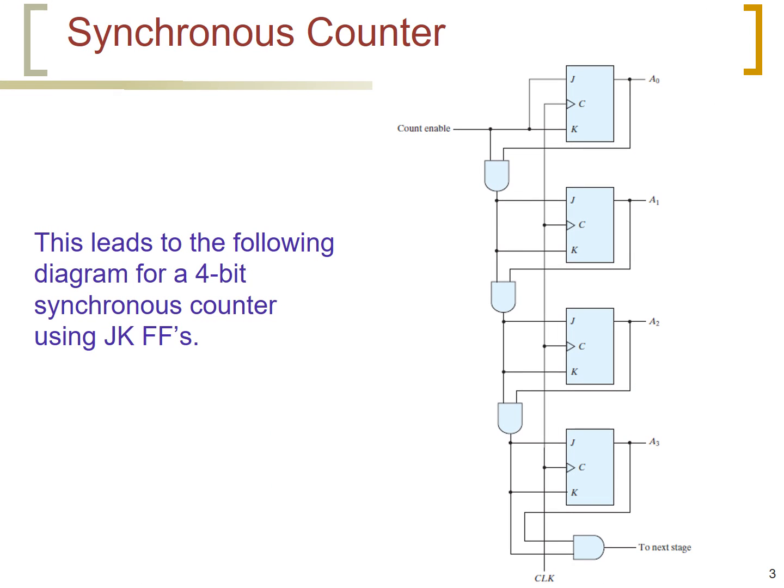The counter can simply be designed as we see in this logic diagram, which comes exactly by following the previous rules that we have just described. In this diagram, we use JK flip-flops, and we call the flip-flops A0, A1, A2, and A3. So the counter will be A0, A1, A2, and A3. A0 is the least significant bit, and A3 is the most significant bit. And we have one common clock that is connected to all the clock inputs of the flip-flops, as we can see here.